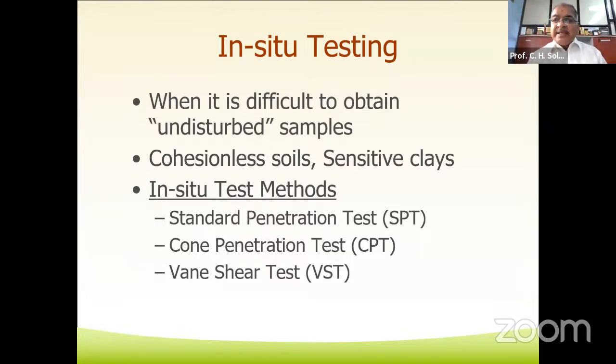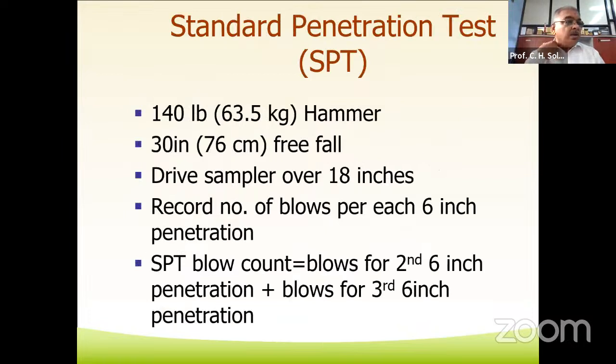Whereas the vane shear test is mostly useful in the case of very soft clays as well as marine clays. These clays are very sensitive. You may be aware of the standard penetration test. What is this test and how is it conducted? We are using a hammer of 63.5 kg. The height of the fall of the hammer is 76 centimeters.